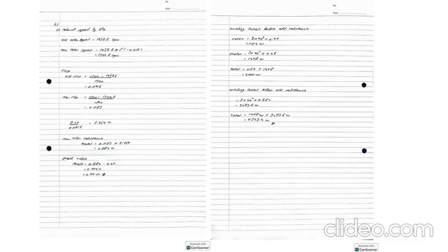Next step is we calculate the slip for the old slip and the new slip. For the old slip we use the value 1437.6 rpm, and the new slip is the latest one when the speed of rotor is reduced by 8%. From that we use the value 1322.6, where the answer for the old slip is 0.0416 and the new slip is 0.1183. After that we need to calculate the resistance, where 0.24 divided by the old slip 0.0416, and we got the answer around